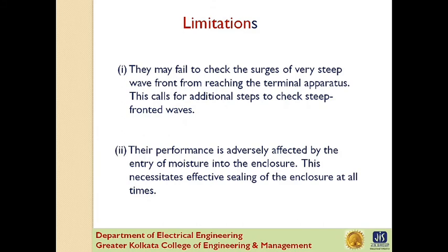What are the limitations? They may fail to check the surges of very steep wavefront from reaching the terminal apparatus. This calls for additional steps to check steep fronted waves. Their performance is adversely affected by the entry of moisture into the enclosure. This necessitates effective sealing of the enclosure at all times.